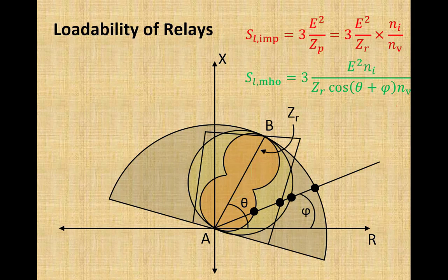So shape 8 relay characteristics are actually modified admittance relay characteristics. Two admittance relay characteristics are overlapping. One is a circle passing through the origin, the other is an offset admittance relay characteristic. Okay, next we discuss the challenges in the protection of parallel transmission lines.